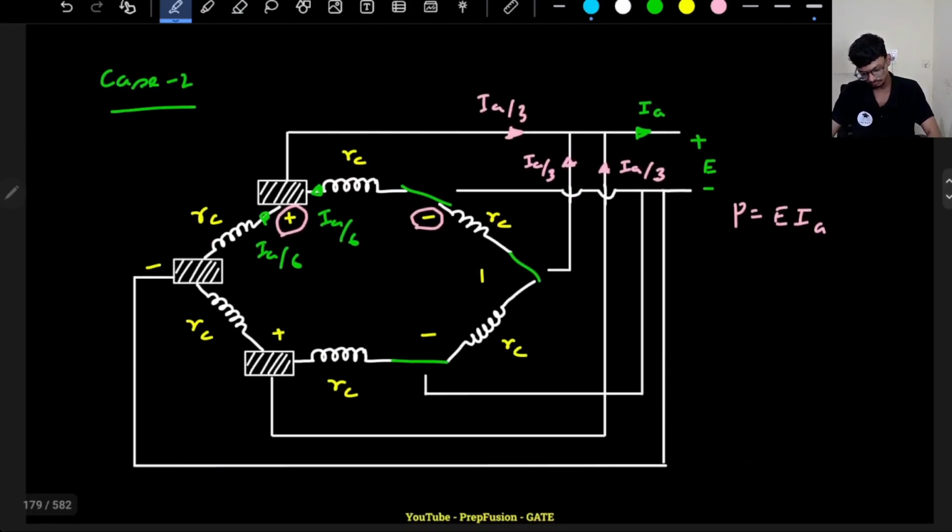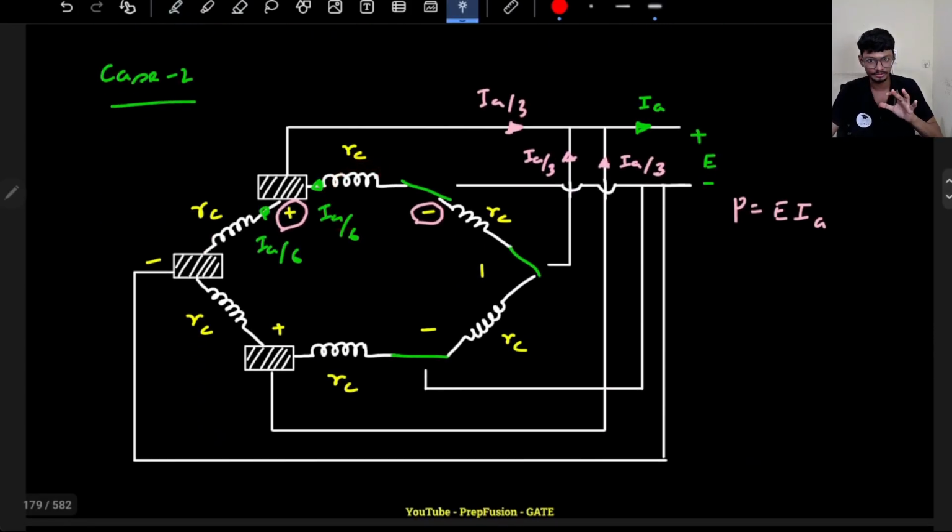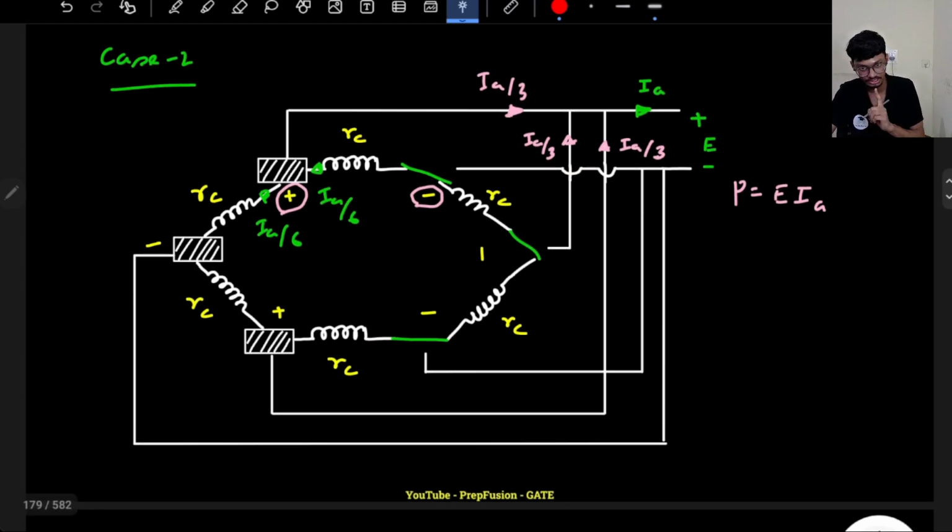So here all the coils will induce their EMF, but brushes are not there, right? So they are simply short circuited, right? Because inside the machine, in lap winding, the positive terminal is connected with the negative terminal, but the brush was there, due to which current was flowing out, and the brush has been removed. So these paths have been open circuited now, right? Only the coil connections are there. So now the interesting fact, voltage will still be induced, right?